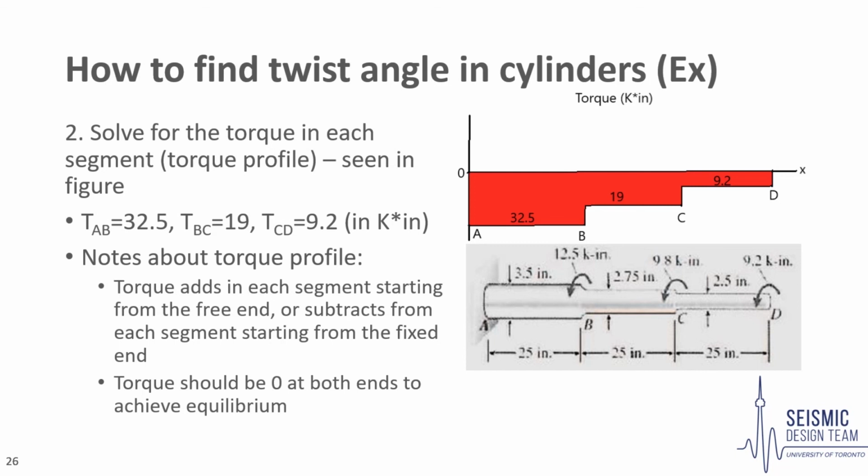Some general aspects about the profile to note are as follows. If we start from the free end, the torque adds in magnitude in each segment, or if we start from the fixed end, the torque subtracts in magnitude in each segment. The torque should be 0 at both ends to achieve equilibrium.